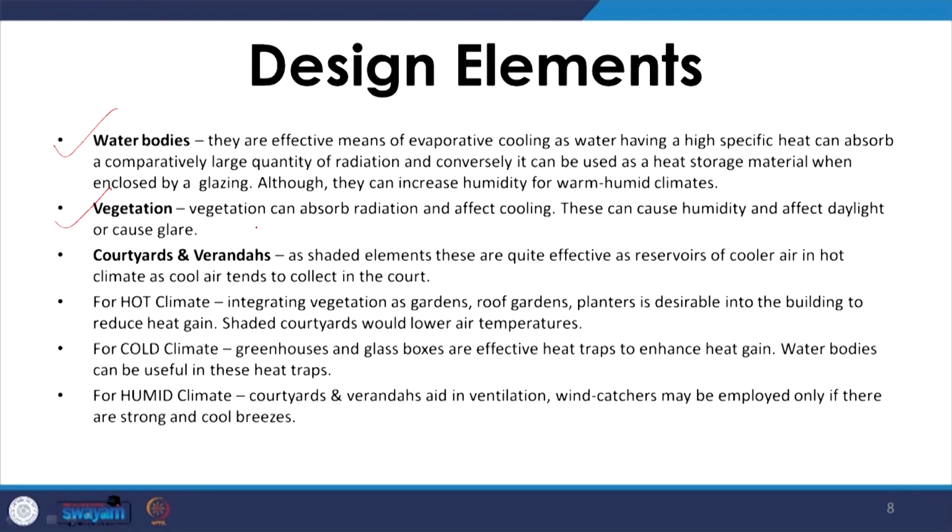Similarly, water body, if it falls en route, the air from where the air is entering into the building in the direction of wind, the air can pick up humidity, moisture from the water body and add to the moisture. So in a hot dry climate, a water body planned in the route from where the wind is entering the building is preferred, while in a cold climate it may not.